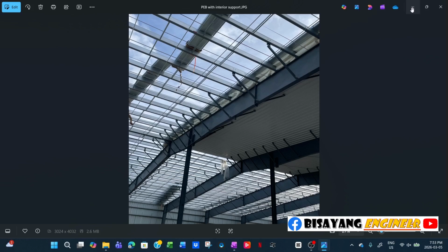And then near the support where you have a negative bending, the bottom flange is in compression, so you increase the bracing spacing accordingly. As long as your details match your assumption, then it should be fine. Otherwise, for example, if you assume it's laterally braced and then you don't provide bracing in the actual, that's a problem. I've seen this when I did a third party inspection for a metal building manufacturer. This is one of the items that I really have to make sure matches with the design.